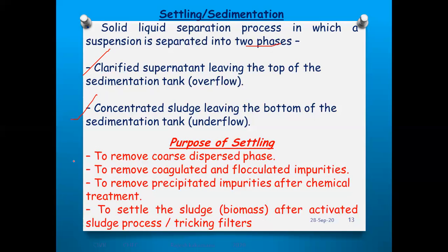Right? Next, what is the purpose of settling? What is the purpose of doing sedimentation in the sedimentation tank? The first thing is to remove the coarse dispersed phase.